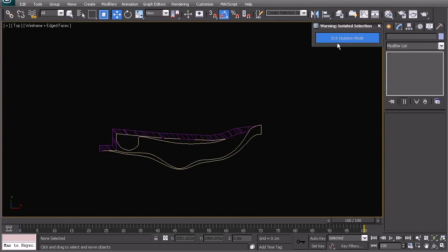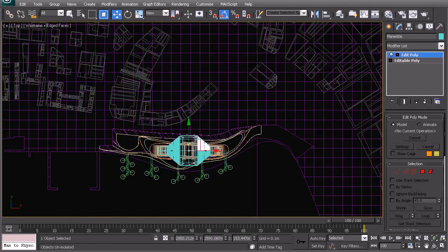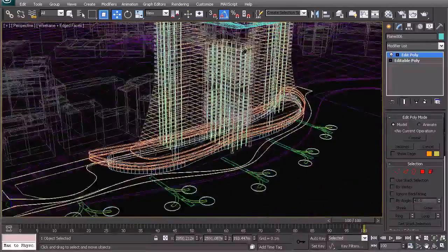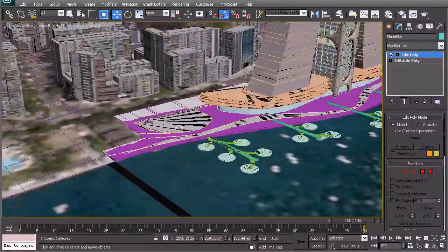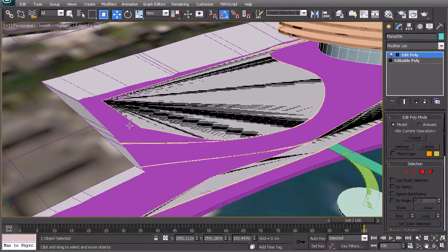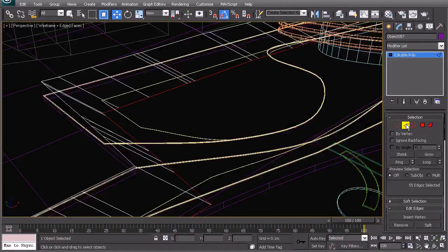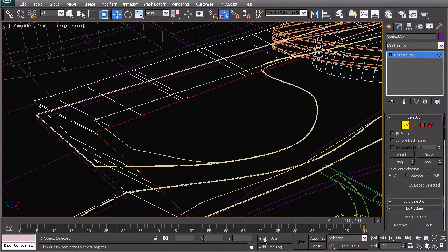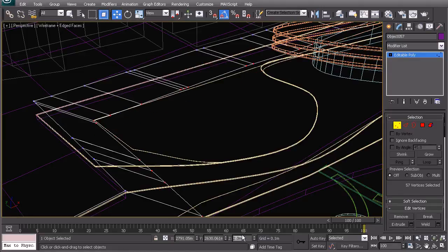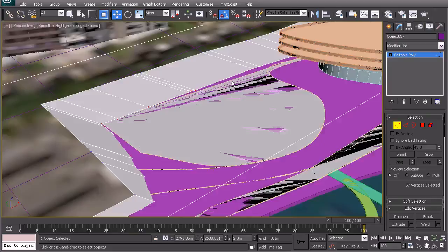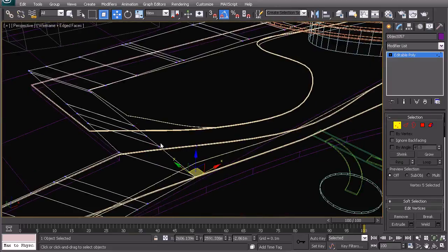And let's go back into our entire model. And let's just have a look at which areas we will be adding grass to. Now we want to add grass here to this area. We want to add grass there. Now we need to move up this bottom line of that berm to 2 meters, which is the height of our platform podium.